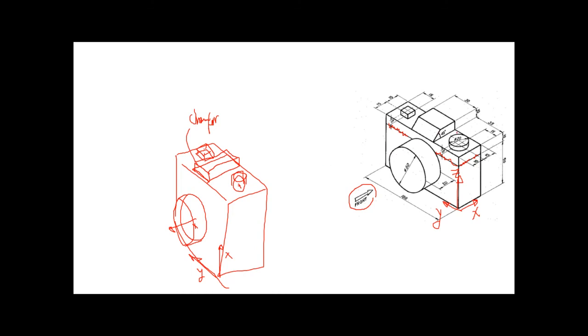Very simple, guys. If you look carefully, this angle is how much? This angle is 45. So what we can do is imagine that I have an angle here making 45. See, guys, I'm just going to look at that side. This is the side of that box, and then your angle is 45. This means that the chamfering distance here, which is the height, is 10. We should have another 10 from that side. Why? Because the angle is 45.